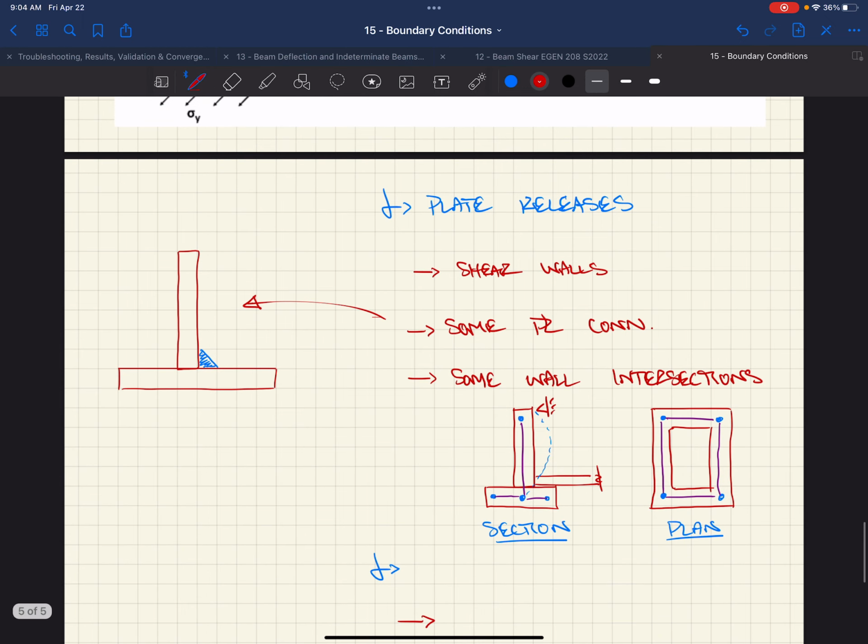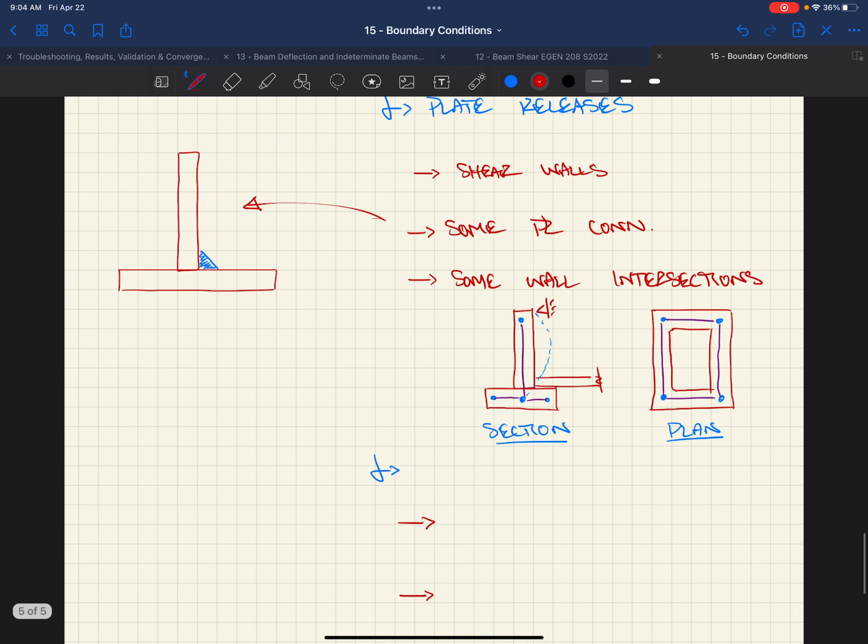We've got to consider the fact that plates can be very, very stiff elements in plane. When we affect the boundary conditions for in-plane performance, we can really affect the stiffness of the model in a big way. So we have to be methodical and thoughtful on how to do this. One big thing with plates is we can do membrane action, right? You remember?